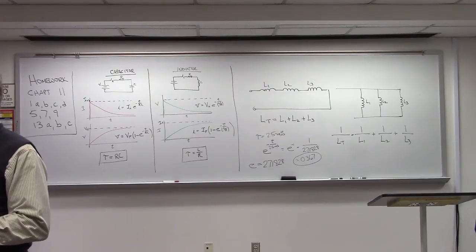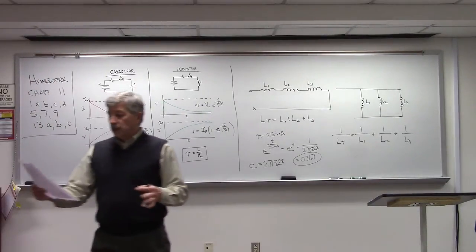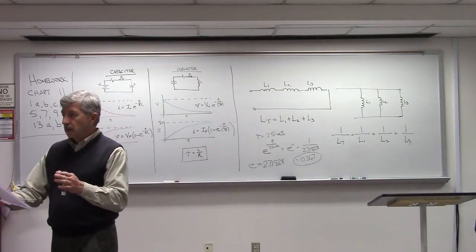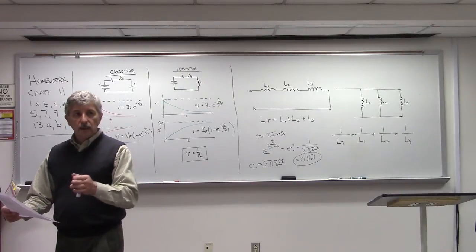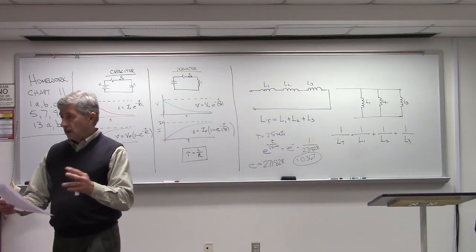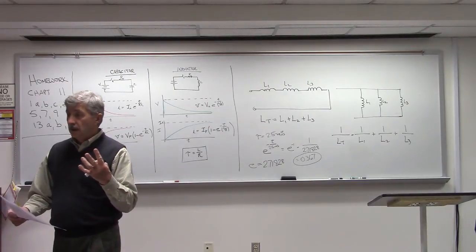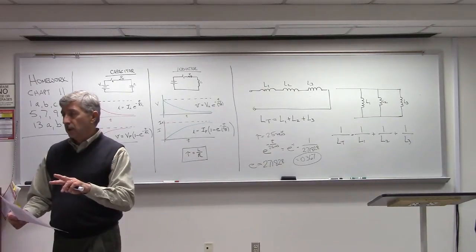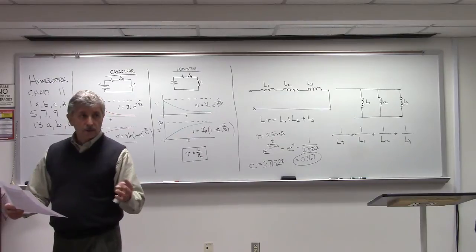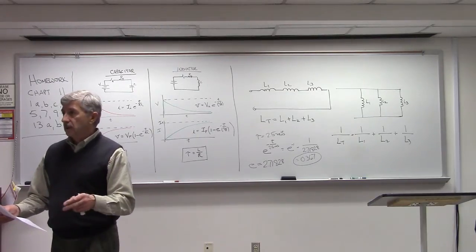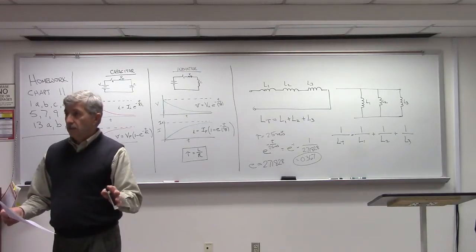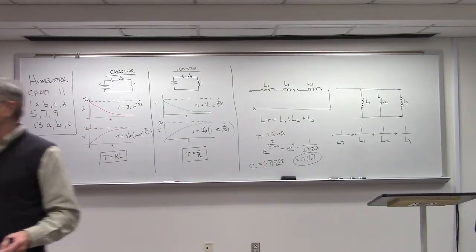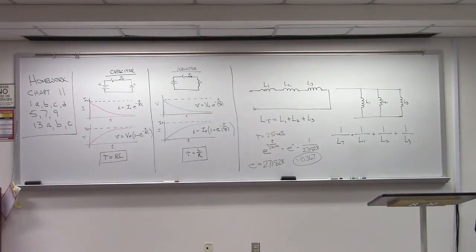So this particular lab, same kind of deal. I'm going to have you build a circuit, but it's a little bit more complex. It's going to be a resistor and a capacitor in series, and a resistor and an inductor in series. And we're going to be using a 4-trace Multisim. So one trace is going to be on the inductor part, another trace on the capacitor part. You're going to get multiple waveforms on the screen. I want you to see how the voltages and currents interact for the inductor and the capacitor. Hopefully I got the values squared away and this will work. All right. So try that. See what happens.